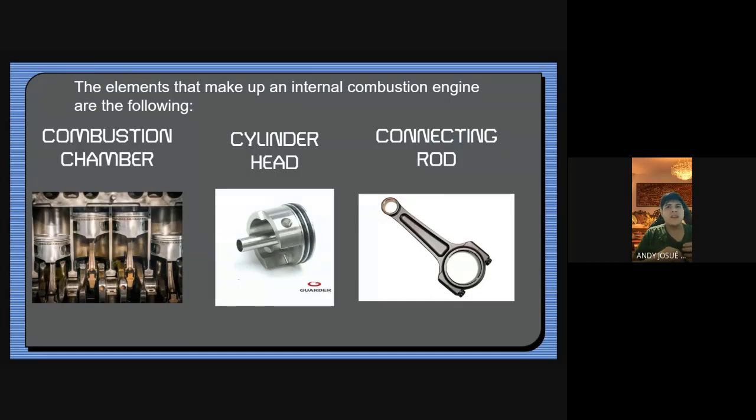Cylinder head. It is the upper part of the engine in which the cylinders are closed at the top, and the intake and exhaust valves, the spark plugs, the camshaft, the air and fuel intake ducts, and the exhaust ducts are housed. Between the engine block and the cylinder head, a gasket is placed, which is called a cylinder head gasket, that guarantees a hermetic seal between both parts.